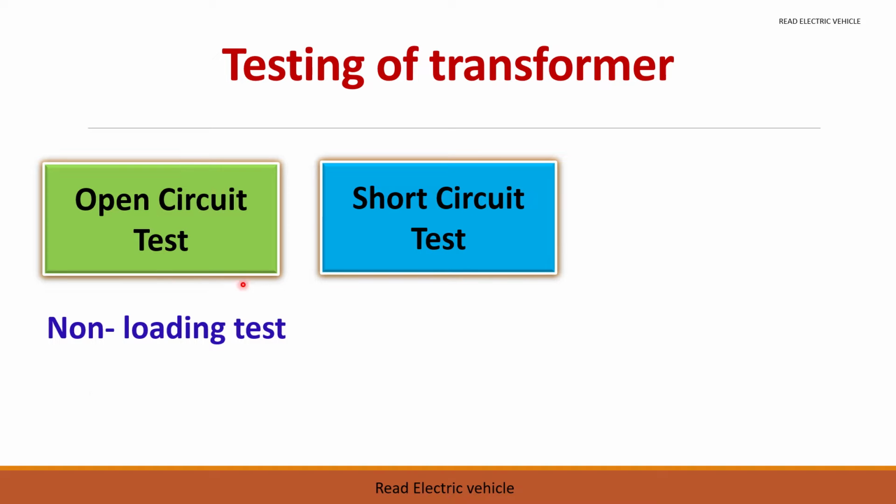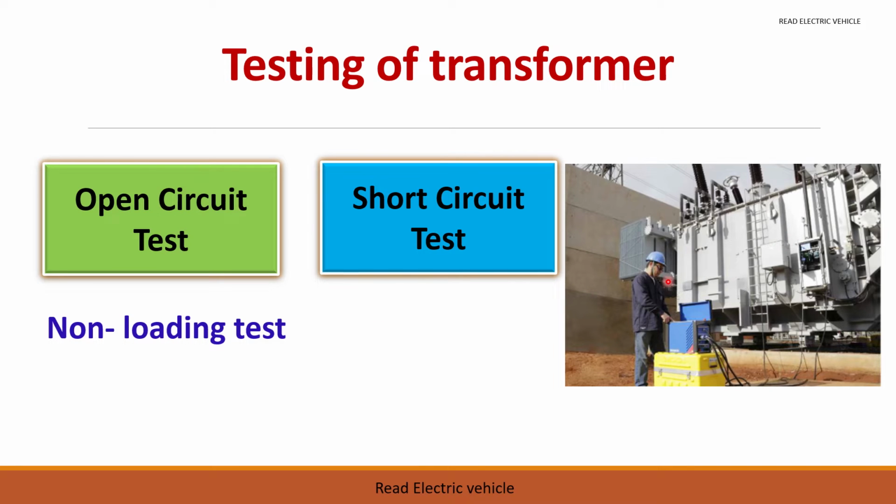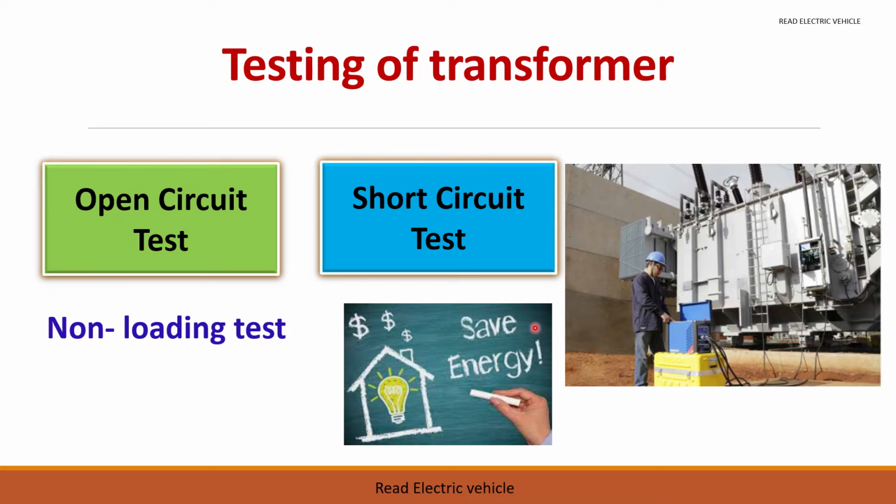These two tests are called non-loading tests because here we do not load the transformer. If you have a large transformer and you want to do a load test on it, it will be a waste of energy because you need a large loading arrangement and a large amount of power will be wasted.